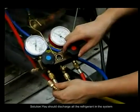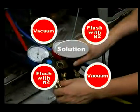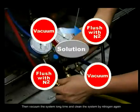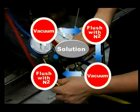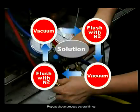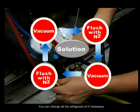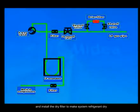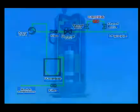Solution. You should discharge all the refrigerant in the system. Vacuum the system long time at first and clean the system by nitrogen. Then, vacuum the system long time and clean the system by nitrogen again. Repeat above process several times. You can change all the refrigerant oil, if necessary, and install the dry filter to make system refrigerant dry.